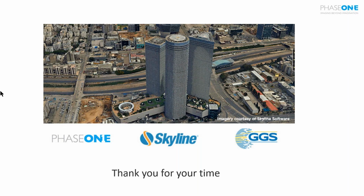How simple is it to produce a DTM from a DSM in PhotoMesh? There's a built-in DTM extraction in PhotoMesh that does its best to remove above-ground features. If there's LiDAR, it does work better with multiple returns.